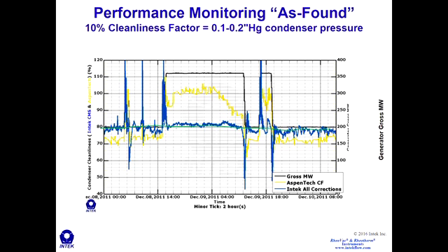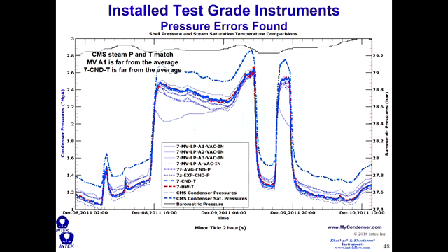They had some unique issues with data averaging. You can see all these straight lines in data averaging, and also some lag in when the measurements were being reported to the historian, which caused these spikes at every load transition. But you can see here very clearly that at low load they're operating at 80%, and at high load they're operating at 80%. So what was causing this? And I want to talk about these because you may use this information to troubleshoot some issues in your own plant.